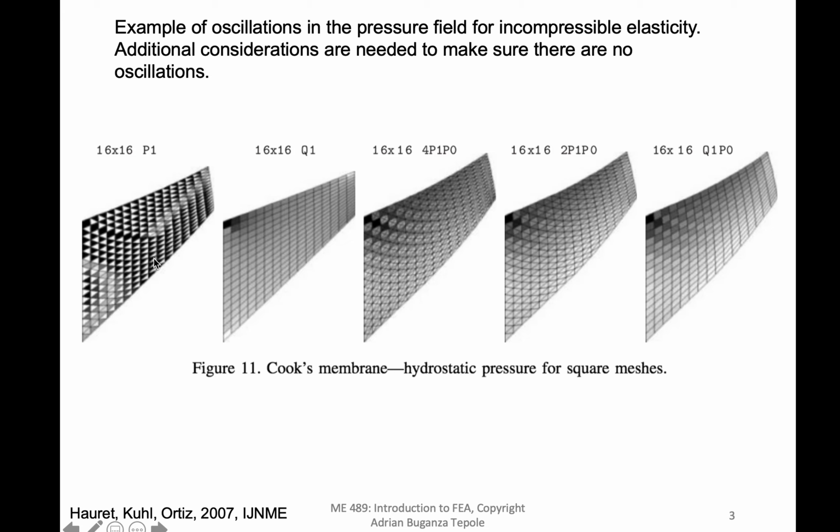So again, I just wanted to have this visual to show these are different formulations that lead to smooth pressure fields. But this one clearly doesn't look right, right? And this type of pattern that you see here, that's an instability. You have these high and low regions of pressure.